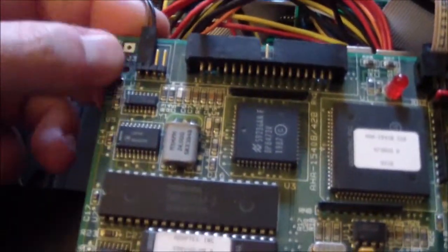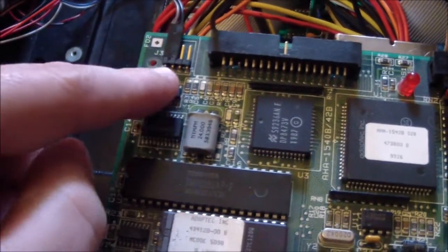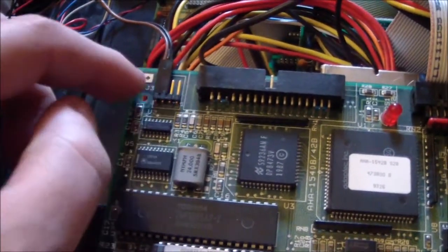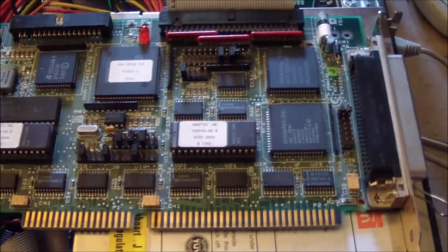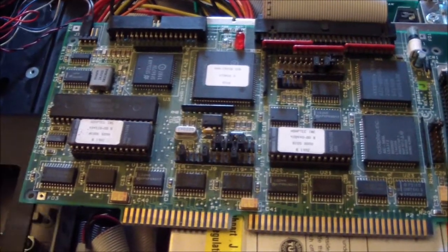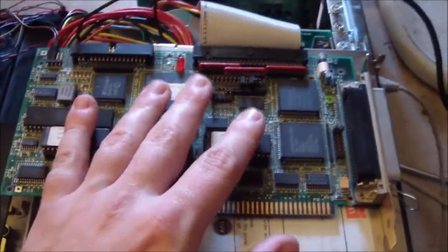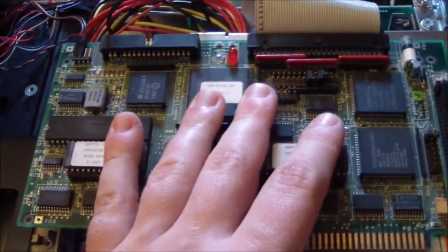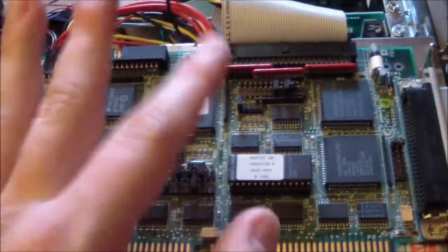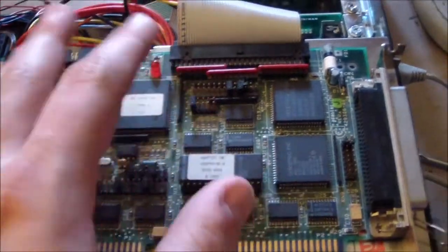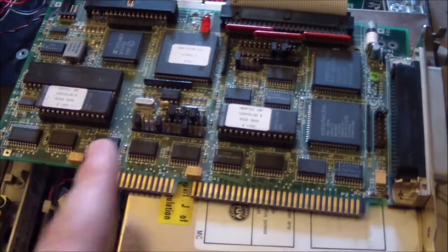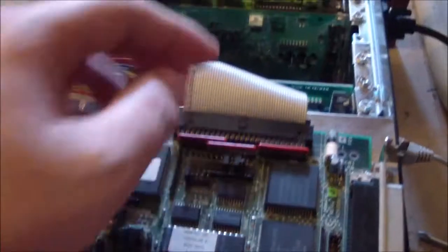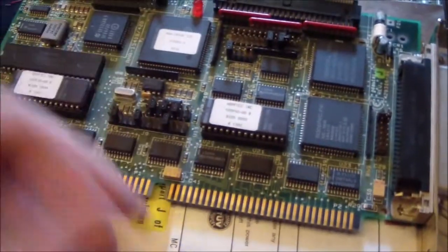It has a header for the LED light. It's a 4-pin, but if you have a 2-pin, you just play around with it until you find where it works. So I'm just going to install this, and then I'll show you the boot up process for this machine. Because I'm only using the hard drive, I don't need to add any SCSI drivers or SCSI Manager or anything. You just install the card, use the 50-pin cable to hook it up to the 50-pin SCSI hard drive, which is down here, and mine started right up. After I figured out the sound card conflict, it works just fine.